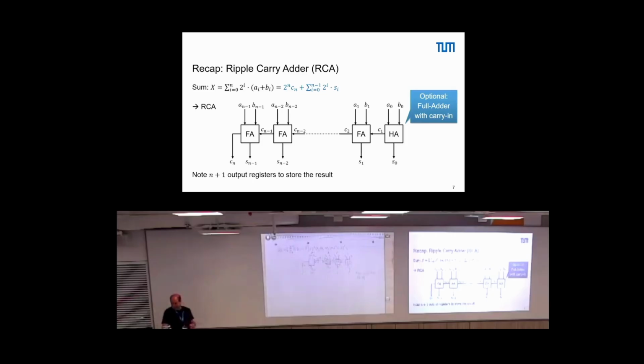Okay. A few remarks because we need this later. First remark, if we look into the structure of this ripple carry adder, of this full adder, then you find here a subcircuit. What is the subcircuit? It's a half adder. So we have here effectively a half adder included in our full adder. That we will use later because we can move all the half adders away at some point and then only focus on this intermediate part. And yes, that's fine for here.